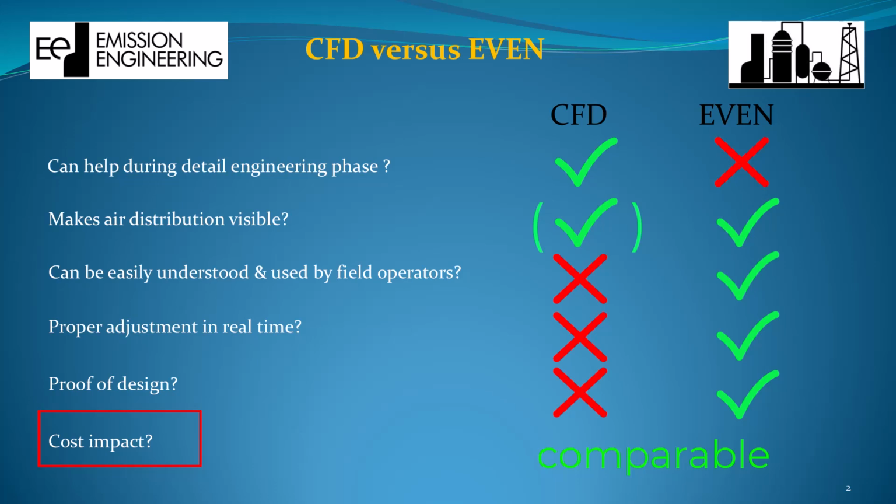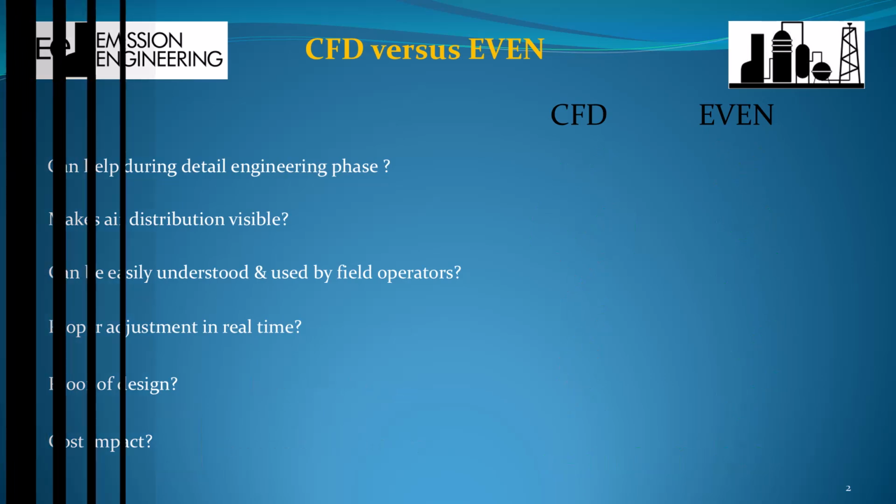Even is also easy to retrofit to existing furnaces and can help you to make safety-related aspects, such as setting the fuel-air ratio on each burner, possible in the first place. The safety standards for such systems, such as DIN EN 746-2 or the successor version DIN ISO EN 13577-2, stipulate such requirements, and only in very rare cases are these met in process furnaces and oil refineries.